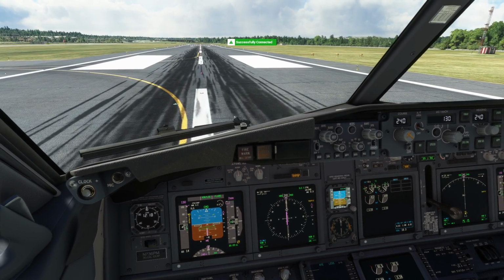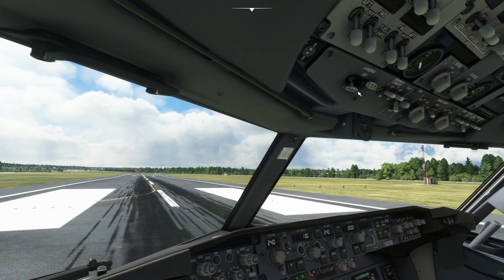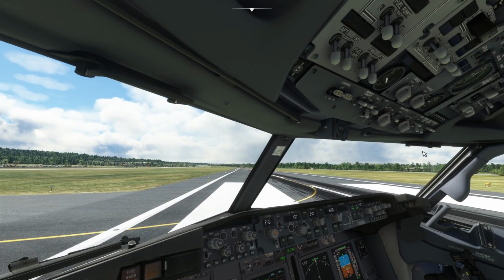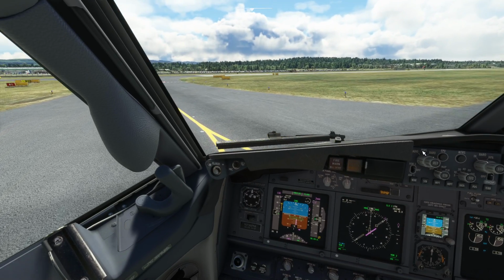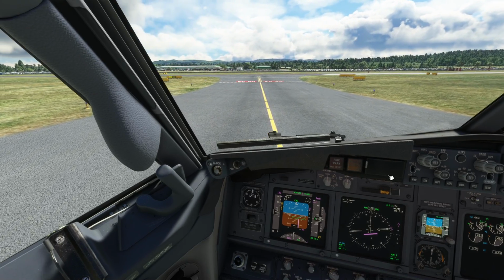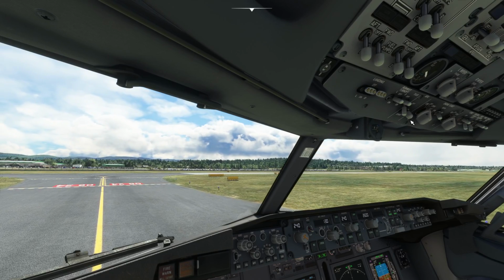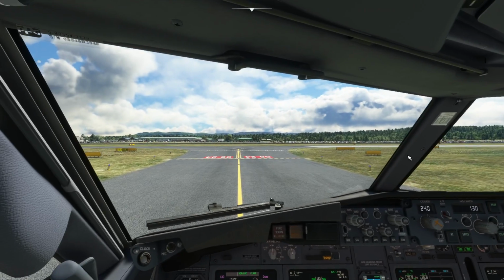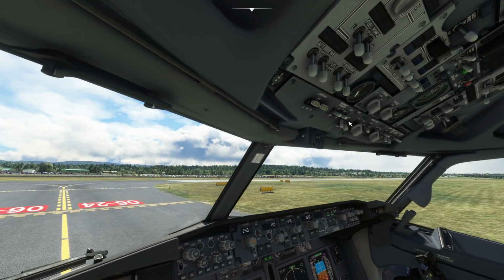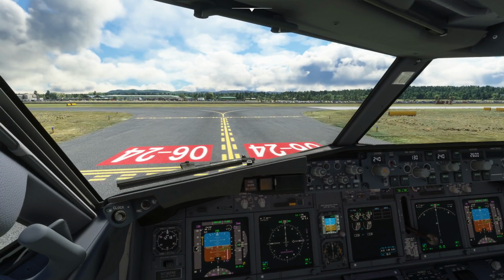So we'll slow down to taxi speeds, and we go and switch off the lights, put the position lights on solid instead of strobing, and on the run into the terminals we can go and turn the APU back on. We have got our taxi light on, haven't we? We have now. No, the taxi light was on. That's fine.